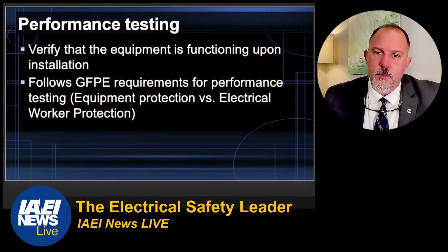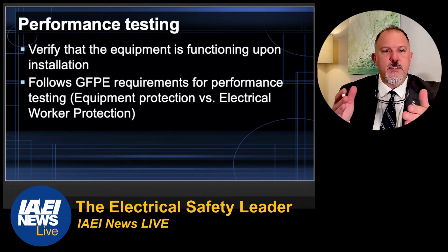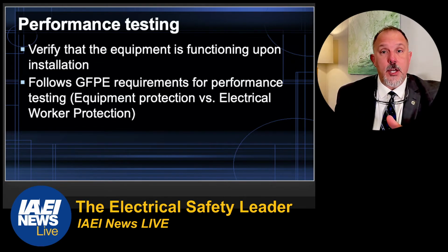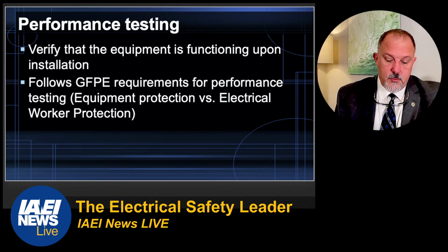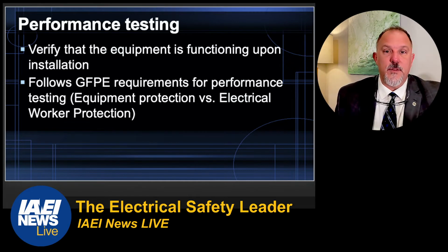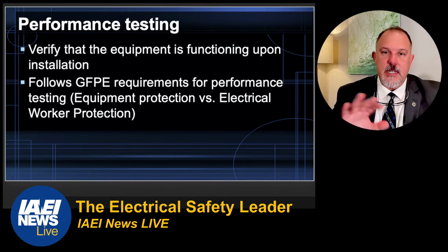Let me find it. There we go. For your performance testing, you're going to verify the equipment is functioning upon installation. We put that in the National Electrical Code because you want to make sure that when you install this equipment, it's functioning on installation. We would rarely do this after the fact, checking the CTs and things like that.